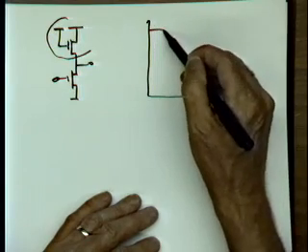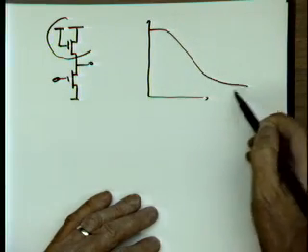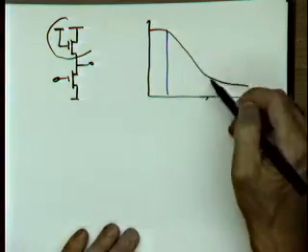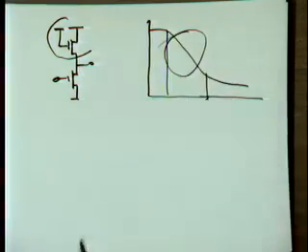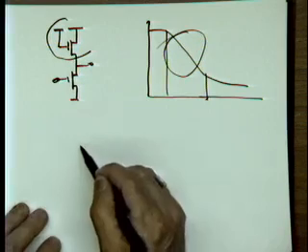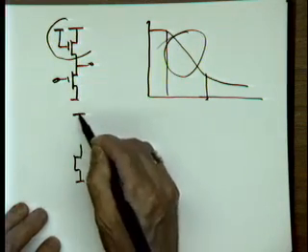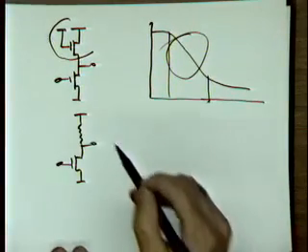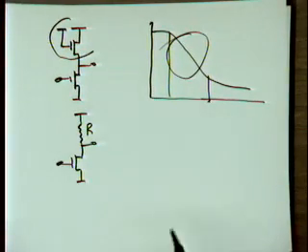It's going to be a kind of iffy thing. It's going to be like this, right? That's what you kind of get. But you still see that I have a very nice region here of regeneration, of gain. So this gate is regenerative. I'm not sure what other NMOS gates you've seen, but for instance, if I have a resistor as the load, again, that is a regenerative gate because it will have gain in the transition region. So these are all regenerative gates.